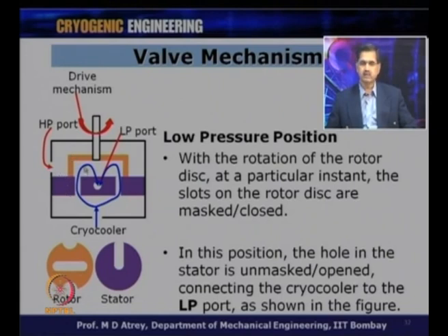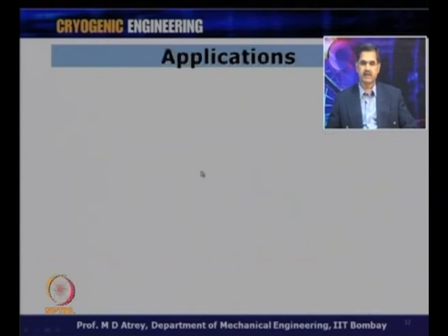This is a very important aspect. Otherwise, the gas can get short circuited. The HP can get in touch with LP and the gas can just flow like this. This is very important. Therefore, this should ensure that the rotor and stator are absolutely leak tight. They are hard pressed against each other.